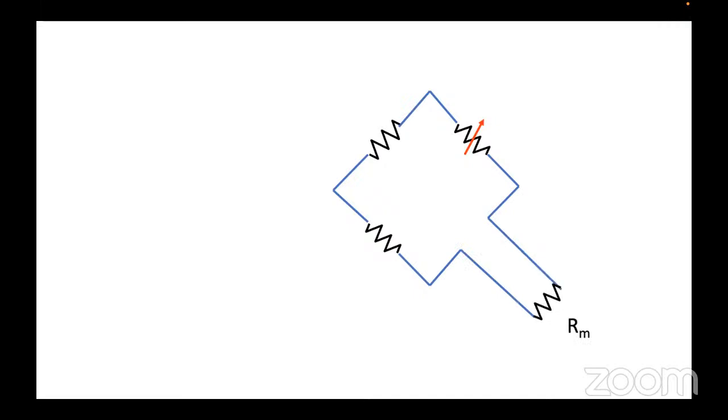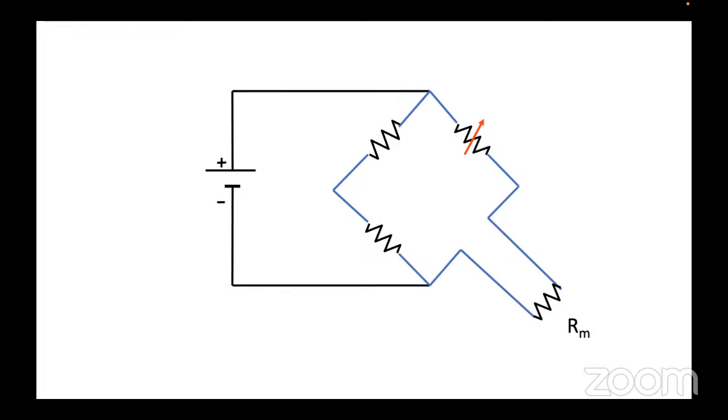How do you monitor an unknown quantity? So what we do here is that you have a measuring resistance. One of the resistances, for example, in the case of a transducer for monitoring blood pressure, is called a strain gauge. So you have a wire. As it stretches, the resistance on it increases. As it comes back to normal position, the resistance goes down. And by comparing the resistance, we can measure what the pressure is that is being applied to a diaphragm, which has this part of the strain gauge.